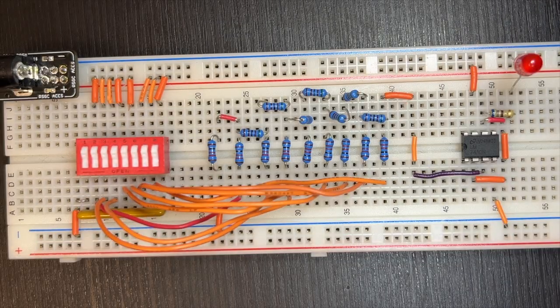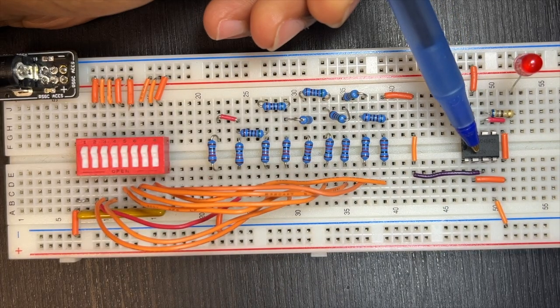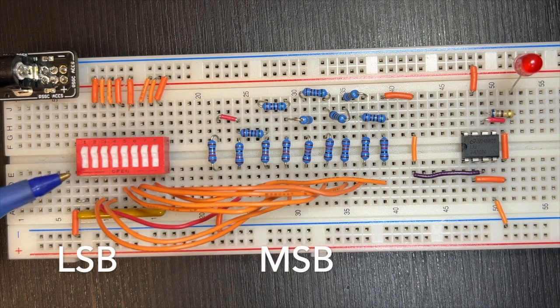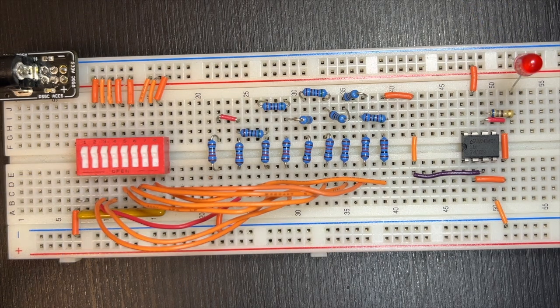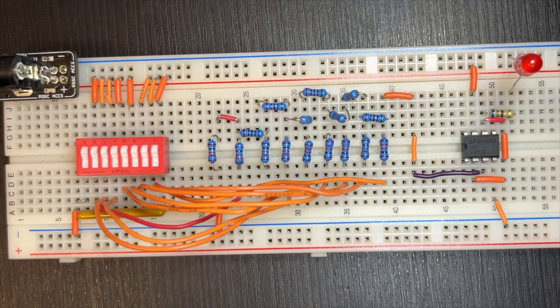As you can see, in this functioning breadboard prototype of the R2R DAC, there is the use of a 9-volt battery, an LM741 op-amp chip, a 5mm red LED, an 8-position DIP rocker switch bank, a bus resistor, 7 5.1K fixed resistors, and 9 10.2K ohm fixed resistors.